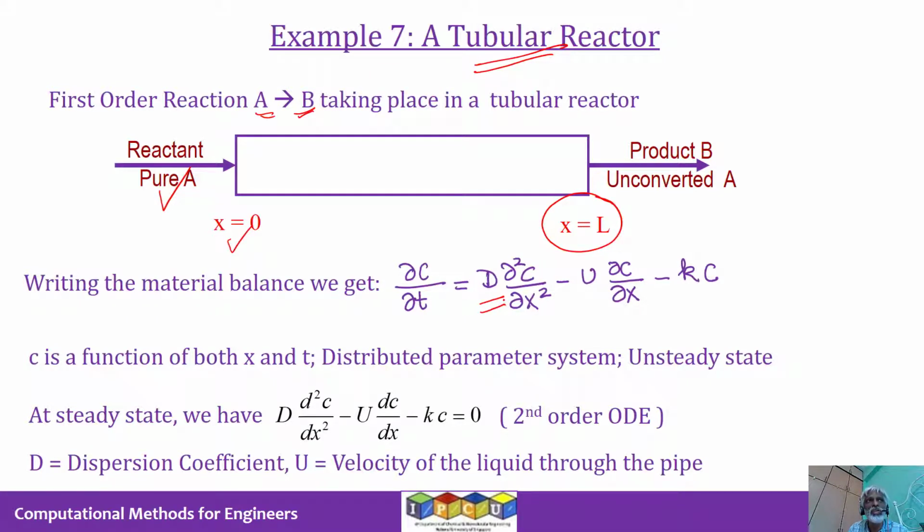So this is related to Fick's law, which you probably have learned already or will learn soon, right? It's called Fick's law of diffusion. So the term has origins from there. So if that phenomena is important, then you have to bring that in. And that phenomena is important typically when you have tubular reactors as opposed to plug flow reactors.